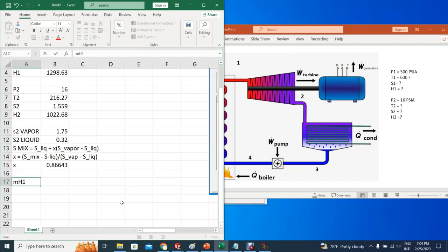We know that our enthalpy is H1. Now, that is in, minus whatever is coming out at point 2, which would be the same mass flow times the enthalpy H2. So power in, power out, and also this is out, so you can say minus the power shaft out as well. And that should be 0. Again, we are saying that this is adiabatic, no heat coming out of this process.